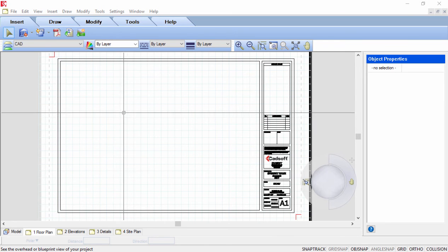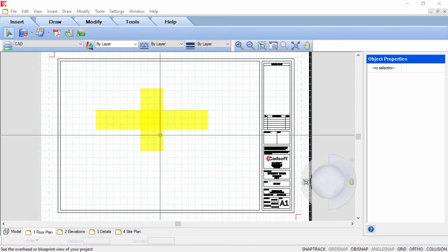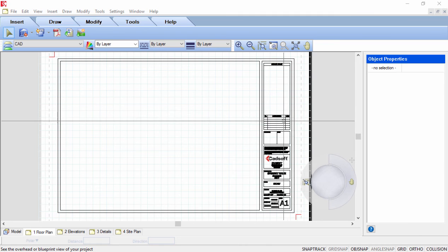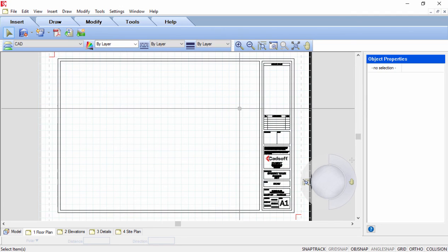In Worksheet View, you can see crosshairs, which are lines that represent the two coordinate axes. At the center of the crosshair is a pick box, a square used for selecting objects. When you move your pointer outside the drawing area, you see a cursor, an arrow, for accessing menus and toolbars. The cursor can also become a double-headed arrow when resizing windows. The Object Properties panel displays the properties of the currently selected object, such as the layer it is assigned to. You can edit properties by simply making different selections in the panel.